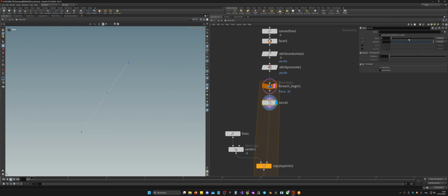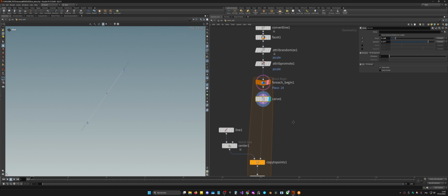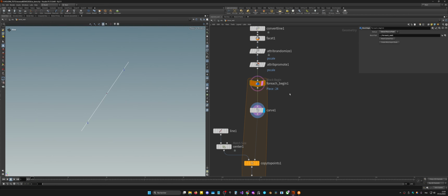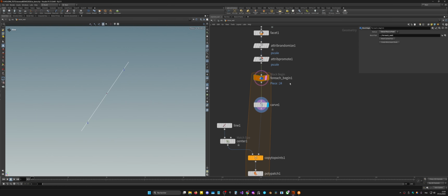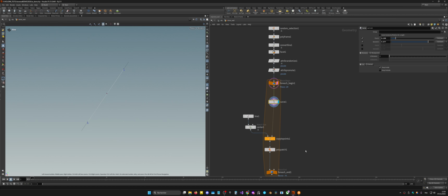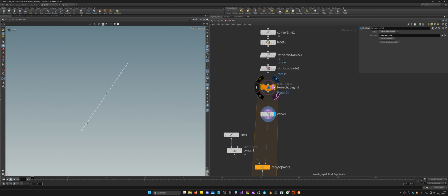And maybe I would like that value to be random, or maybe I will add it later. If I want it random, I should go to the loop import node that will create information on the loop. I will get the iteration count, and I will use it as a seed in a random expression there. So every edge will have a different value. Or let's make it. Select the first node of your loop and create import meta.